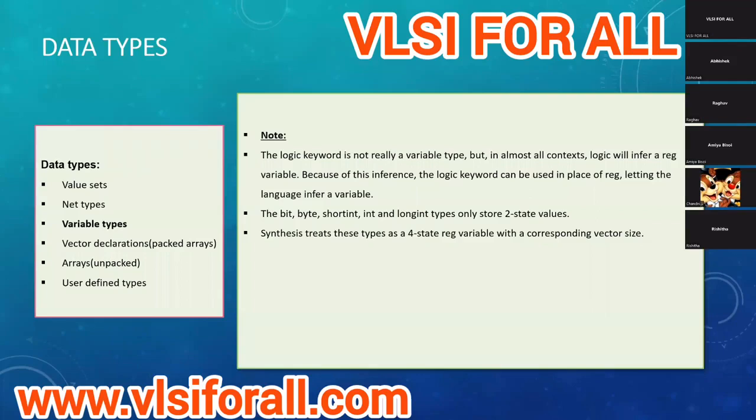So you have to synthesize that design first. So you have to create a netlist. So netlist is basically a representation of your design which you wrote in HDL in terms of AND gates, OR gates, and these basic primitive gates. Now, when we have the netlist, then we do static timing analysis and placement, routing, power analysis. So at that point of time, everything is 4-state because anything can be 0, 1, X or Z. Okay, so basically this is the difference you need to understand.